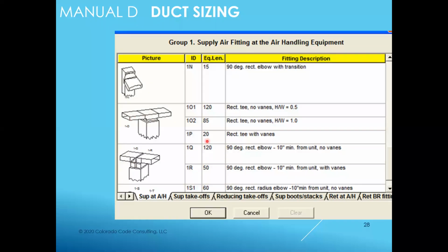What do we normally see? The tightest thing we can possibly make, and it's 120 feet long. We just added 100 linear feet to that ductwork in one fitting. So the air comes up without the turning vanes, and what's it doing? It gets all confused, just going, hey, what's going on? And then 120 feet later, it realizes, oh, hey guys, we could go either way.